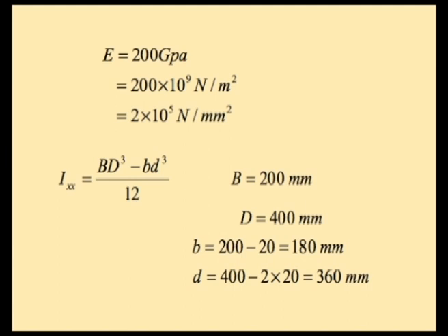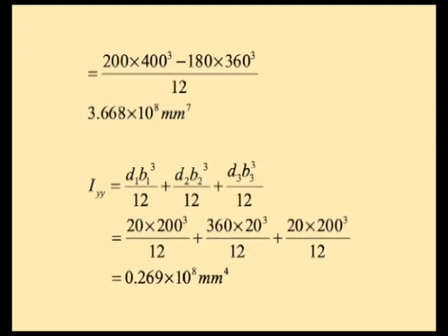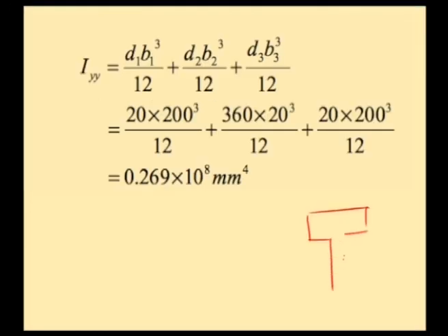And then for moment of inertia, we need to calculate I yy as well as I xx, because for a column we have studied both cases, that is bending about x axis and y axis. So, if you are given the column, we need to identify I yy. Similarly, we will also calculate I xx, and we will decide which to be used for the load calculations.